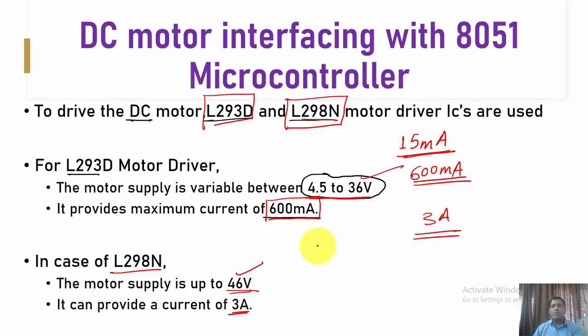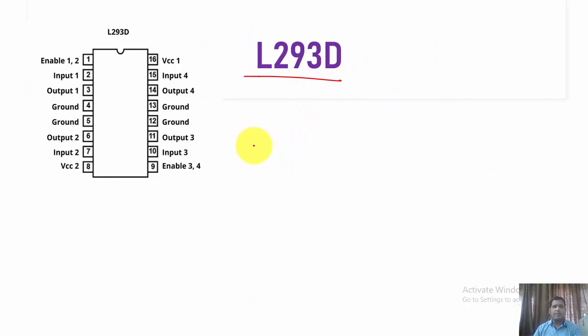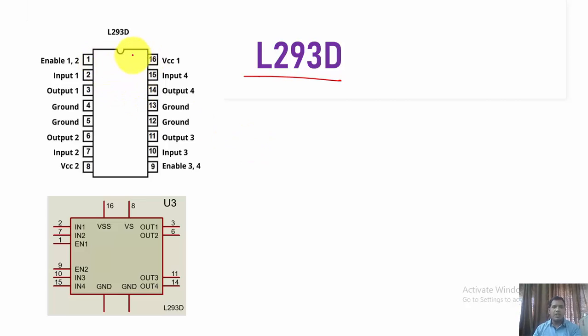So here, when we talk about any automation activity, or I will say a robotic activity, we require what? The interfacing of the L293D with, say, simple DC motor interfacing, with the central controlling unit, and that can be done through this motor driver IC. So let us talk about L293D, the motor driver IC, right? This is the pin configuration. This is basically a 16-pin IC, right?